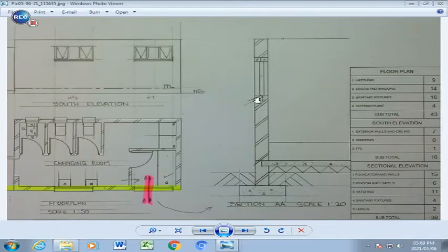And then of course also they give you the details of the window sill, which should be placed like that at a 30-degree angle. That's the window frame that we have there. That is the concrete slab. Just keep in mind that that extra little line there is the DPC, which I have not labeled, but it's important for you to label that. Then of course also the natural ground level should be labeled there as well.